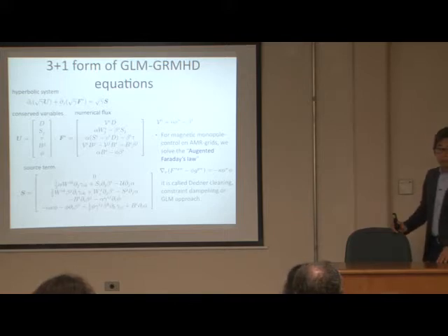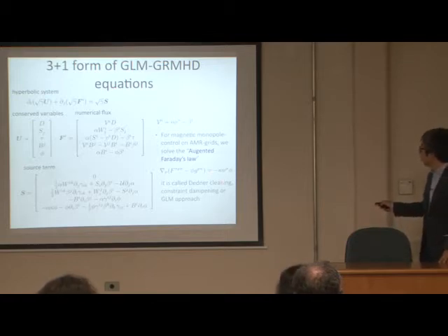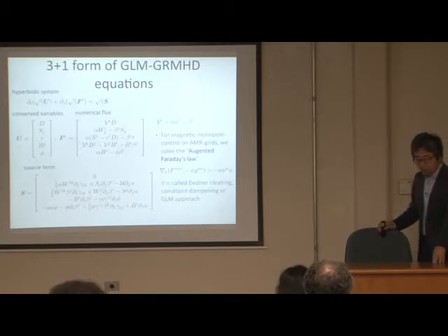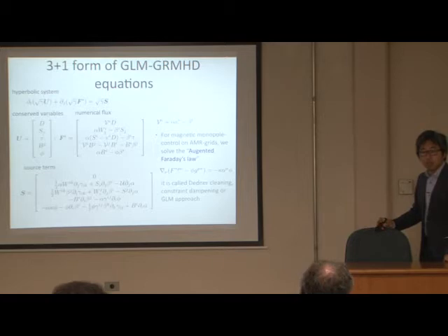What is that for? How does this cleaning depend on this kappa? Yes, this is a damping parameter. This is the propagation and the damping term. So we can arbitrarily choose this damping term as some number. Then how much effect it has also needs some testing. This is similar to the artificial viscosity, but this is for adaptive mesh refinement.